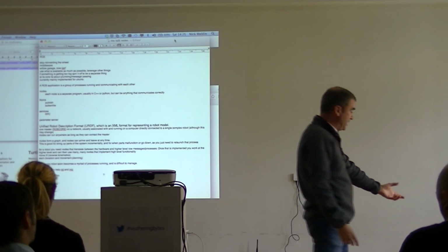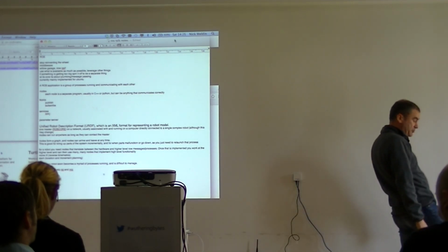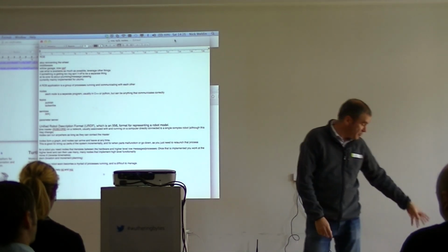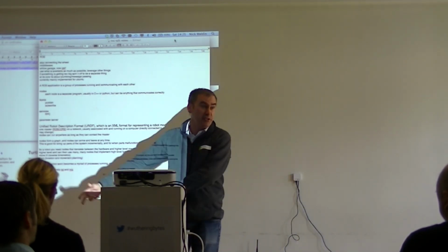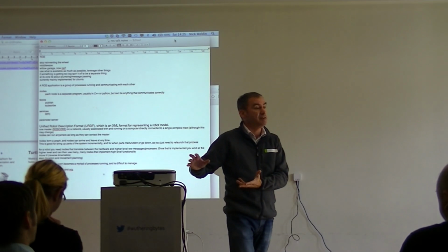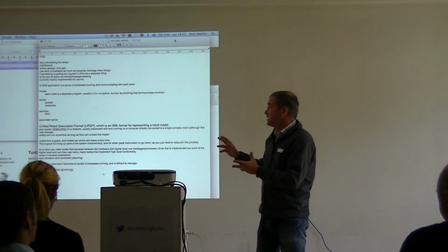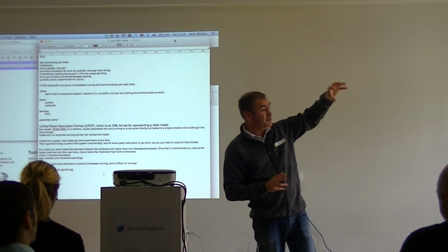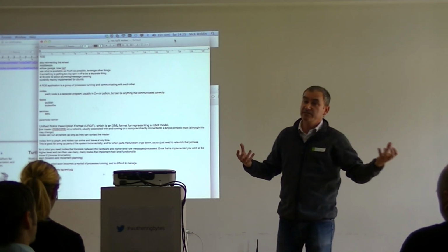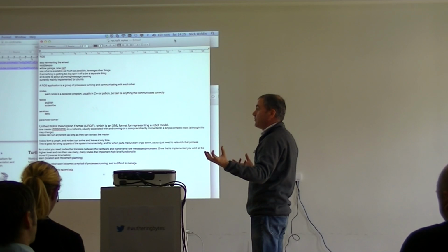So there would be nodes, for example, that would know how to talk to a Kinect. So for this robot, you would launch those nodes. If you had another robot that had a Kinect, you would use those nodes with it without having to rewrite them. And the URDF would take care of all the transformations that needed to happen because the Kinect was sitting in a different place on a different robot and was physically configured differently.